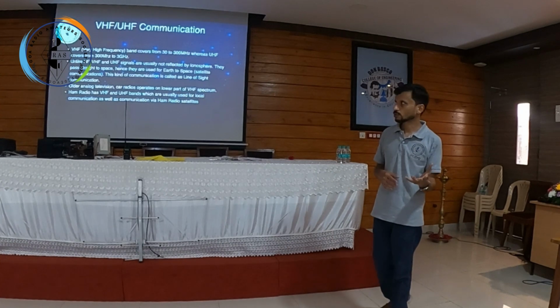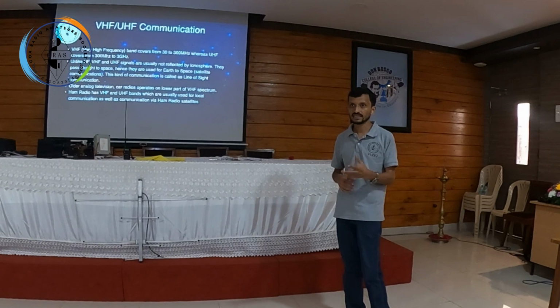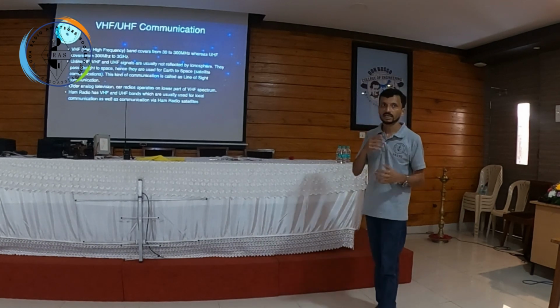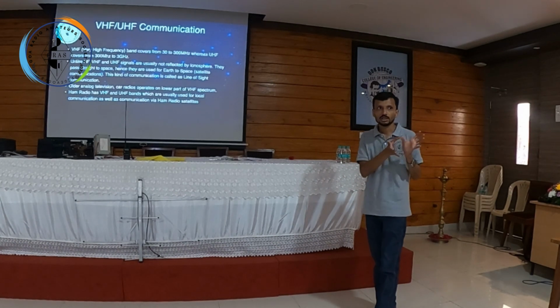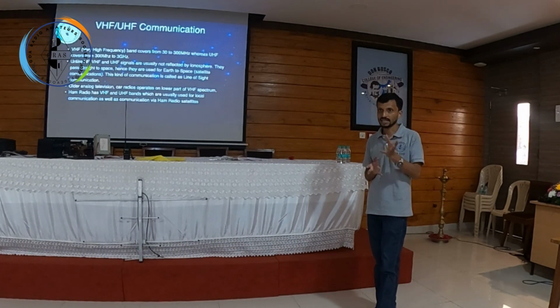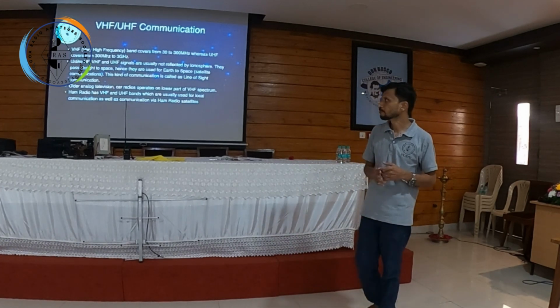Same with dish antenna also. Dish antennas usually are in the SHF bands, that is super high frequency, or EHF bands. So those are for satellite communication. Rather than pointing your antenna towards the transmitting station, you will point it towards the satellite, because that will give a higher coverage all over the country.